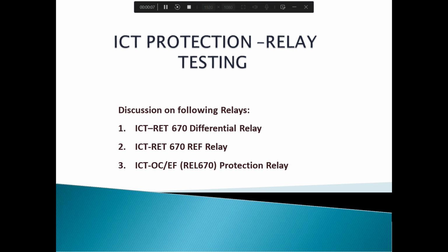And from today onwards, we will discuss the relay testing procedure and relay testing using the Omicron Relay Test Kit. In this session, we will focus on the testing of differential protection relays, followed by REF and directional overcurrent and earth fault protection in the upcoming session.